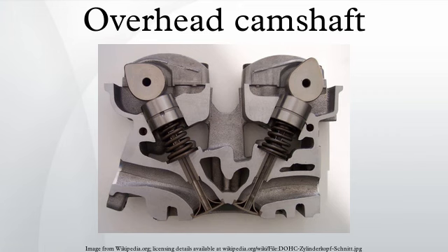In the SOHC design, the camshaft operates the valves directly, traditionally via a bucket tappet, or via an intermediary rocker arm. SOHC cylinder heads are generally less expensive to manufacture than DOHC cylinder heads. Timing belt replacement can be easier since there are fewer camshaft drive sprockets that need to be aligned during the replacement procedure. In the early era of the liquid-cooled aircraft engine field, single overhead camshaft format engines were in existence during the First World War, for both the Allies and the Central Powers.